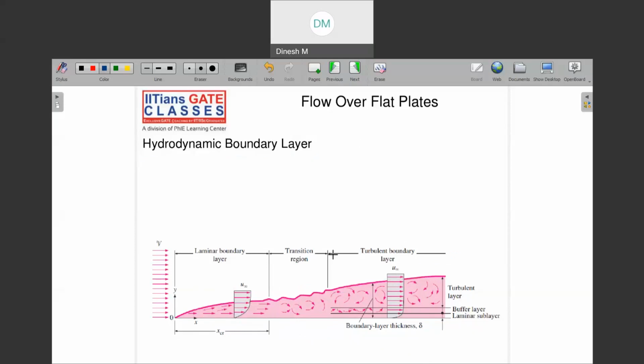One thing. And second thing now is that the flow inside this boundary layer is rotational in nature. Okay, one thing. And second thing, if this is rotational in nature, then you cannot apply Bernoulli's theorem into it. Bernoulli's theorem you must know. Then there were certain assumptions, and one assumption was that the fluid is irrotational, but in this region the fluid has got some rotational velocity.